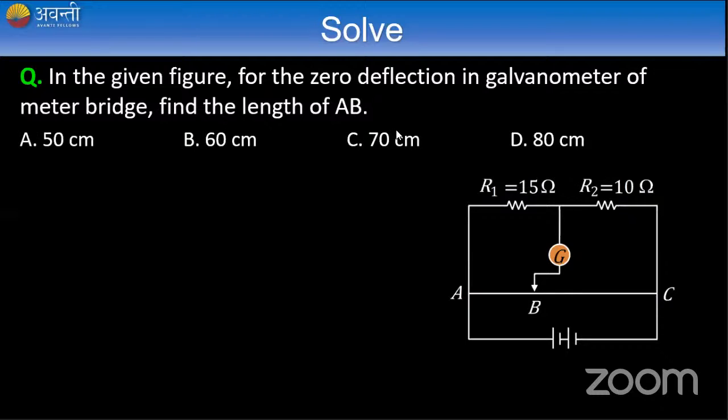Sir, one doubt: in a Wheatstone bridge, if the galvanometer deflects, how can we find the unknown resistance? That's the reason, Hariprasad, the galvanometer should not deflect. We should find the balancing point, so until then we have to slide our jockey. In a properly connected Wheatstone bridge, there will be a null point for sure, one hundred percent, if you have connected all the circuit elements properly. It should anyway satisfy this condition.